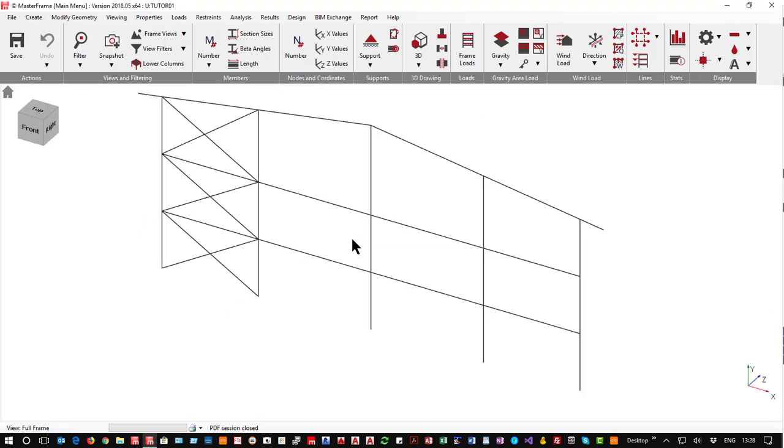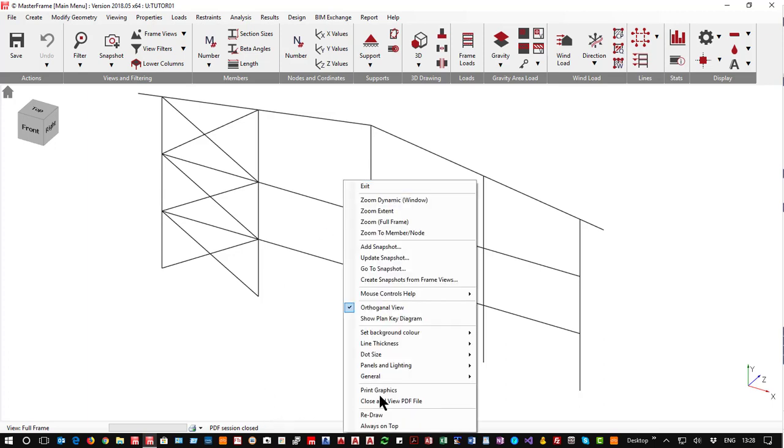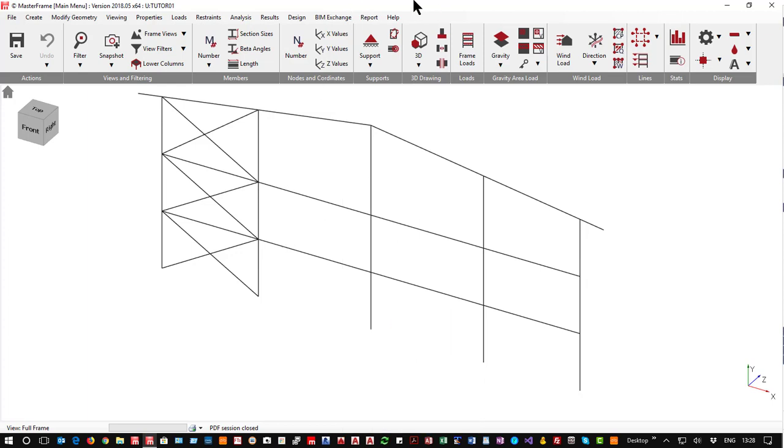And it now comes time to print all that out. First of all, you want to print it out into one output document. So you would come along and you'd go right mouse click print graphics, and you'd show then the bending moment diagrams and everything and do all that. But we have a better way of doing it, and it's this thing called the report generator. So let's go into the report generator.